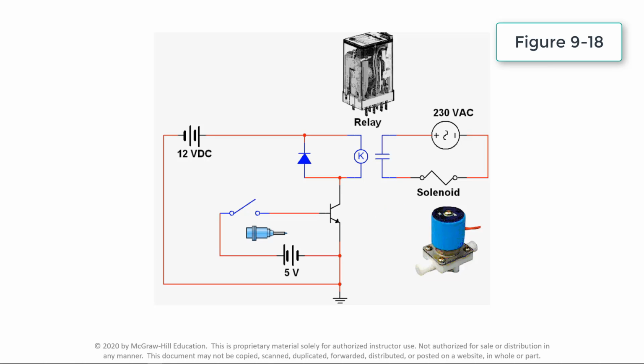This video demonstrates the operation of a bipolar junction transistor switching of an AC load. When a transistor is used as a switch, it has only two operating states, on and off. Bipolar transistors cannot directly switch AC loads, and they are not usually a good choice for switching higher voltages or currents. In these cases, a relay in conjunction with a low-power transistor is often used.